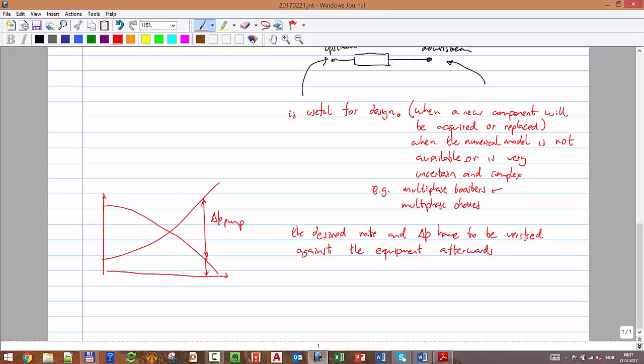But it turns out that the power that I need to pump that fluid is, let's say, something. ESP pumps have a range of power, between 300 horsepower and all the way to, I think, 2000 horsepower. So if you obtain, for example, a power that is 3000, it is not feasible. I will never find a pump that will be able to provide that combination of rate and delta P. Or if you are within the range, let's say you have 700, you have to find the right model that provides exactly that combination of delta P and rate. That clear?